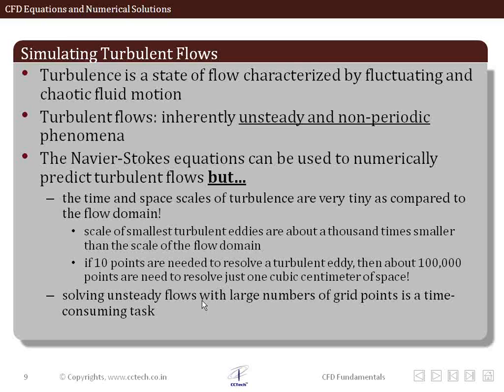And when these inertial forces really dominate the viscous forces, that's when the flow becomes turbulent, very chaotic. And turbulence is quite unsteady and non-periodic, so there is no proper orderly behavior of turbulent flows. So for modeling such flows, we can actually capture them if we can solve the Navier-Stokes equation exactly. Or even if we want to do a numerical prediction of the Navier-Stokes equation, the task is quite huge because it's an unsteady, non-periodic phenomenon in space and time, and it's quite chaotic.